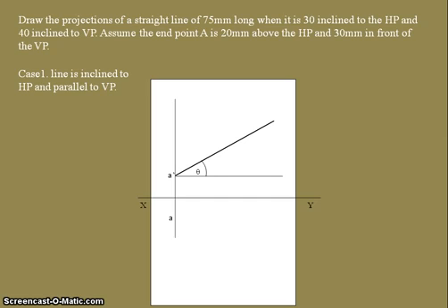Draw a line with true length, that is 75 mm long, and give the end point the name B1 dash. Why are we taking B1 dash? Because it is not the final front view, so we are taking the suffix 1. When we get the final front view we make it B dash only. So here we got the front view for the first case with the true length.